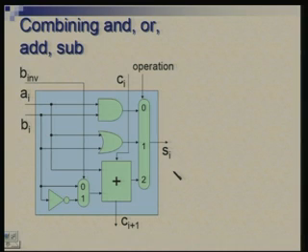Okay. So, this is one module, or one bit unit, of the ALU, which is capable of performing one of the 4 operations, and it needs to be guided by this input, which can have 3 possible values, and this input which can have 2 possible values. Of course, this is ignored, or it is do not care, when you are performing AND and OR operations. Okay. So, when you are choosing this or this, what you are doing here does not matter.